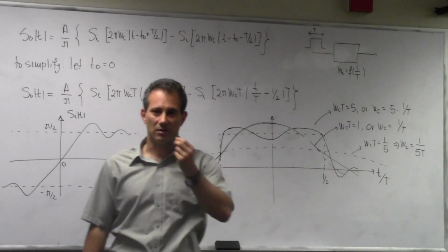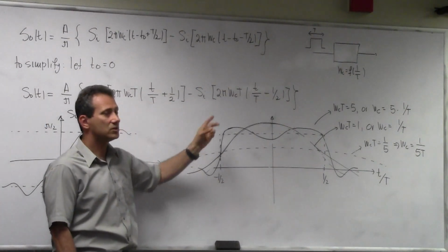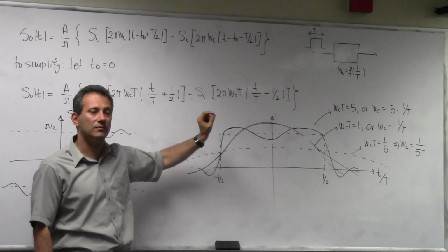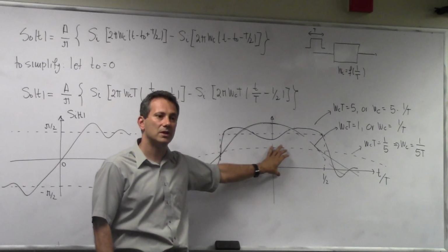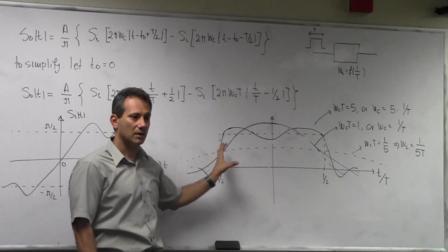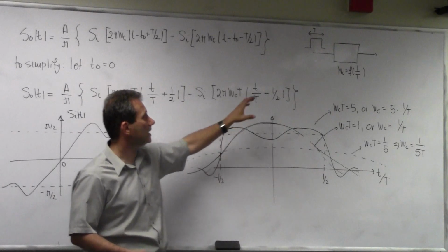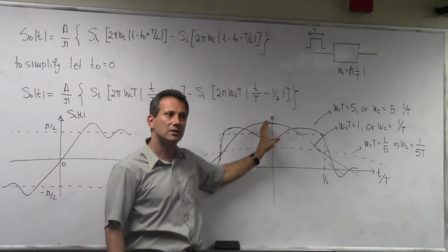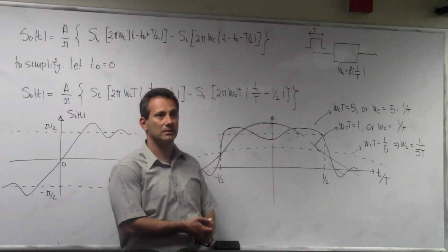So what is the recipe here? What is our course of action? Well, let's not signal with square pulses. That seemed like an obvious one. Let's try to devise a pulse that will have certain properties that will minimize the intersymbol interference, right? So I need to embark on a search for the time domain versions of this s_m(t) such that it does not create interference in the time domain when I receive it.